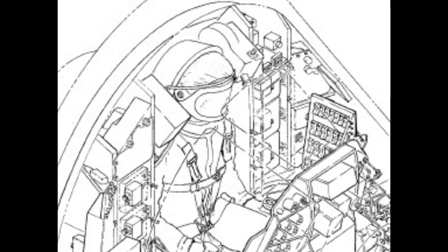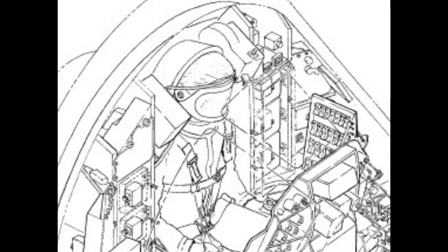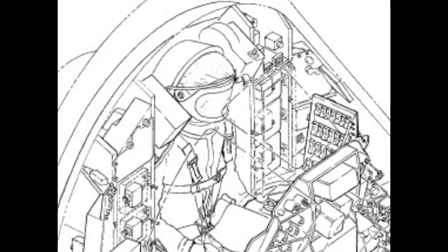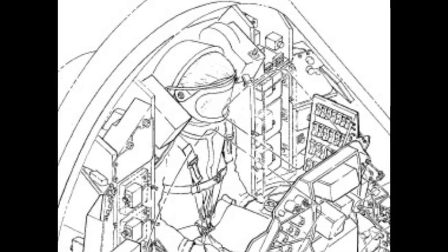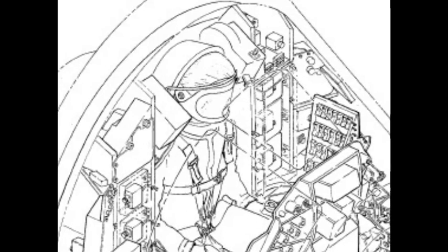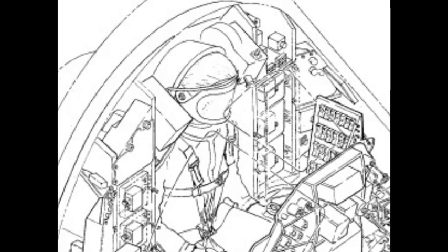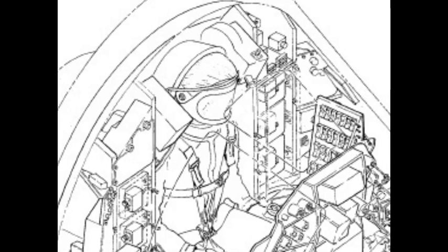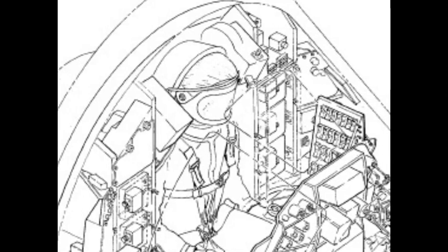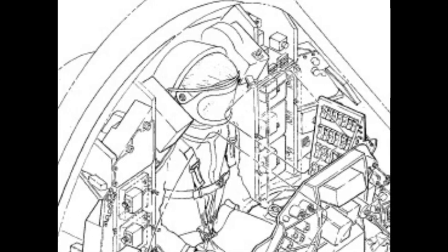214. Pylon capsule clamp ring. The clamp ring consists of 3 chevron-shaped segments that clamp the pylon attach ring to the capsule recovery system compartment flange. 3 explosive bolts with dual ignition provisions connect the ring segments in tension. The clamp ring is basically the same in design as the capsule adapter clamp ring, figure 2.9, but considerably smaller in size. The clamp ring retains the pylon to the capsule until the clamp ring explosive bolts are fired, which in turn separates the clamp ring.